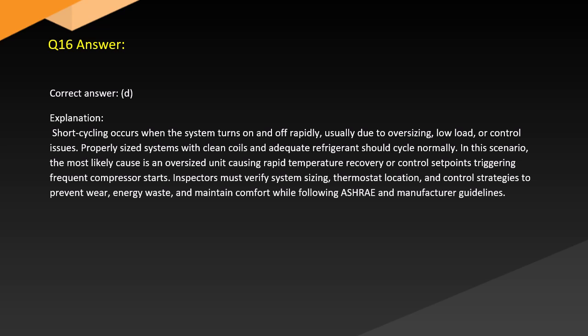In this scenario, the most likely cause is an oversized unit causing rapid temperature recovery or control set points triggering frequent compressor starts. Inspectors must verify system sizing, thermostat location, and control strategies to prevent wear, energy waste, and maintain comfort while following ASHRAE and manufacturer guidelines.